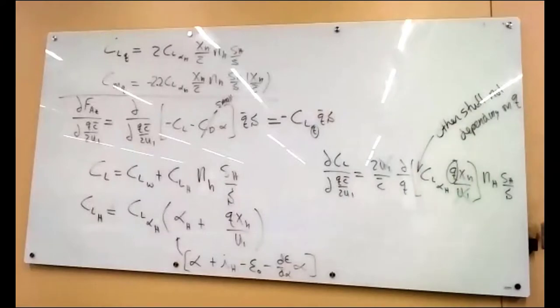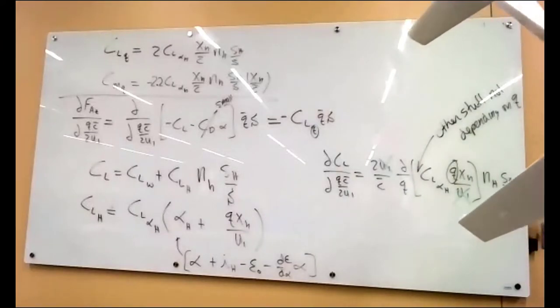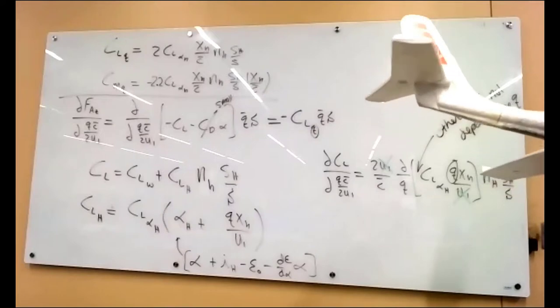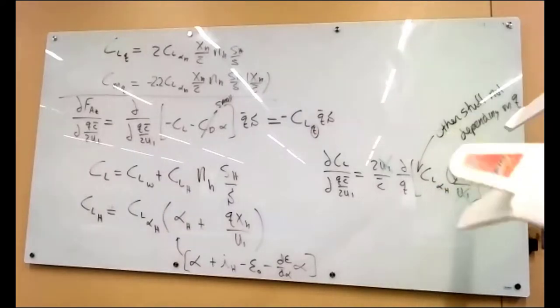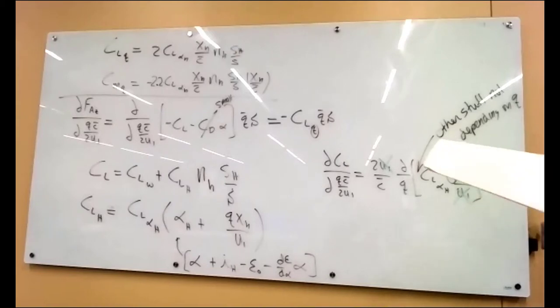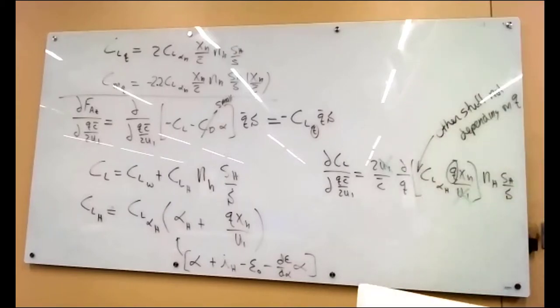Now, if you want to do better than that, you've got to do a full analysis of the lift distribution on the wing and how it changes when you pitch the wing, and that gets more complicated. So preliminary design, real quick calculations, you use that, and then you validate your numbers either with CFD or in wind tunnels. Again, we're engineers, so when you're doing a preliminary design, you don't want a real complicated analysis of every airplane design you're looking at. You want a quick analysis to see what is more viable to explore in more depth.